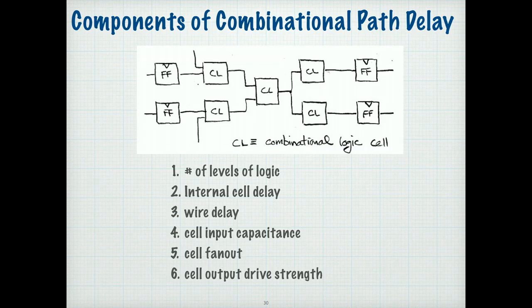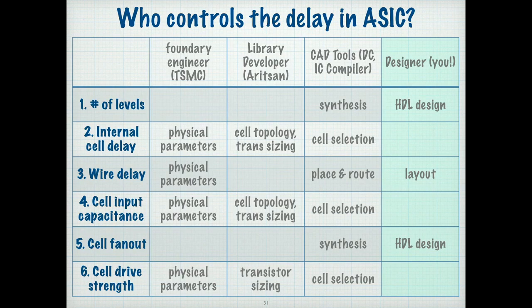And then the transistors inside these logic blocks help determine what the logic delay is too, because if the transistors are wider, they're able to provide more current, more charge per unit time, and therefore their rise and fall times would be smaller. So there are all these components to logic delay, and some of it is under the control of the designer, and some of it is given to you by the tools.